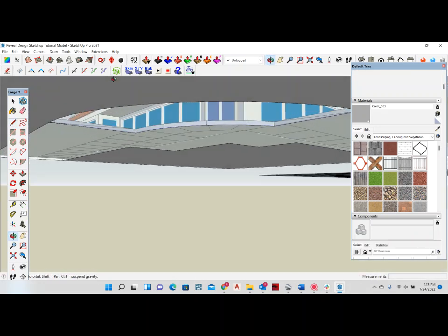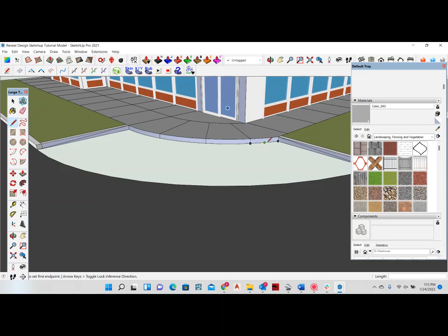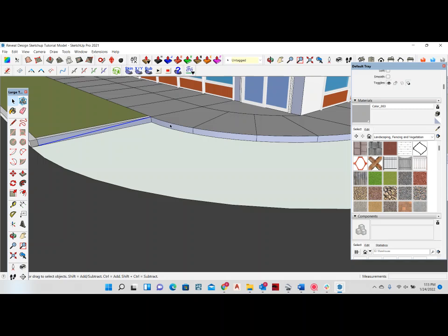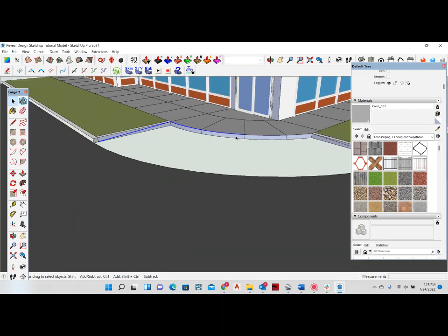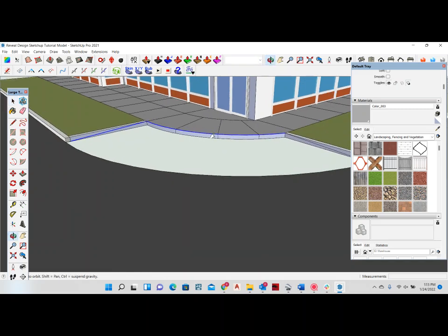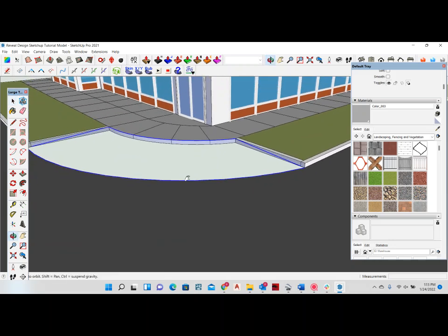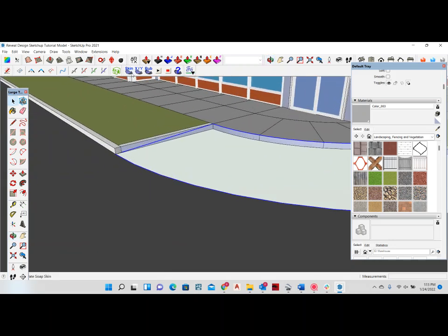As you can see, a face has not been created yet because we have this curve here. It's curved here. It's not on the same plane. So no faces have been created. So what we need to do is create a face with soap skin bubble. And we need to select all of these lines on the perimeter of what we want to face. So we can do that, and everything's selected, and we're just going to hit that soap skin bubble here.